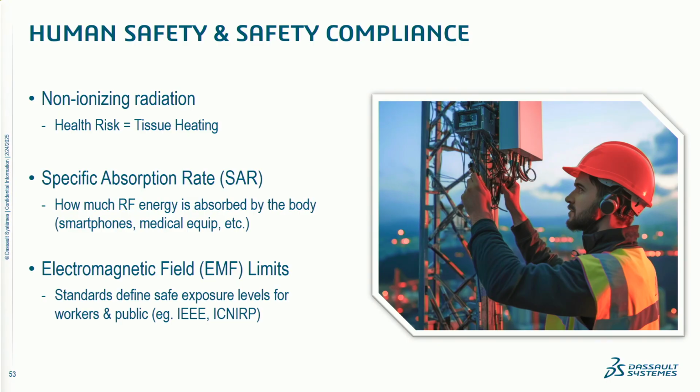Normally, the power levels are low enough and the blood flow pulls enough heat away from the skin that it's not a concern. But when you get into higher powered devices or things that have to be in contact with you for a long time, this can be a concern. You can end up with burns and all sorts of tissue damage. And what we look at for that are sort of two things. For the human body side of it, specific absorption rate. That's the measured value of how much RF energy is being absorbed by the body.